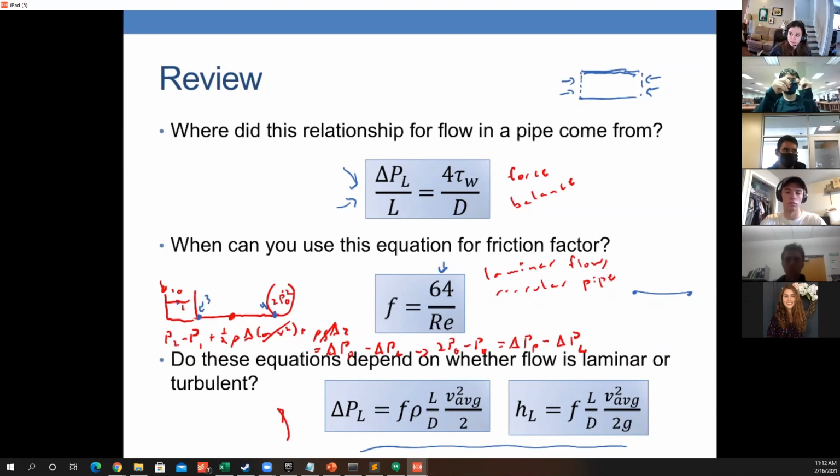At least when it comes to the energy balance. So the friction that really affects the energy balance happens at the wall, because that's where the shear stress is most prominent. So that's where the viscous forces are most significant. So it's just at the wall. It's at r equal to big R. That is how mathematically it would be. So that is how you would get friction.